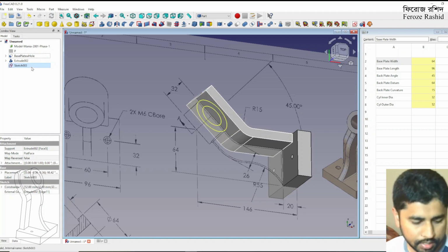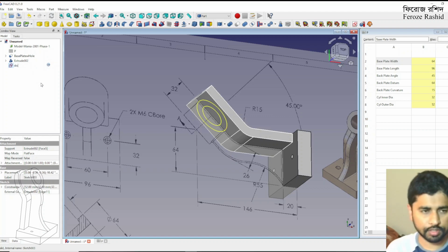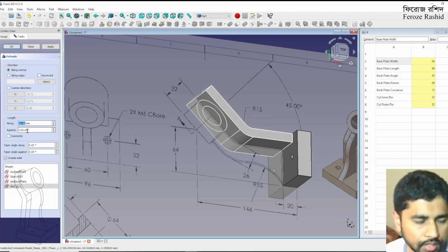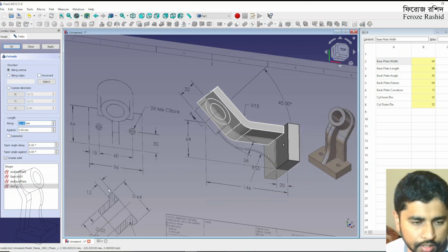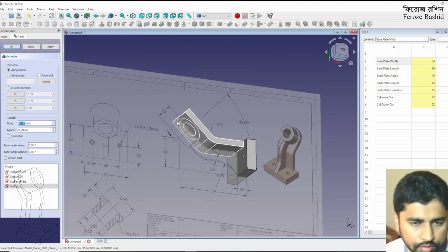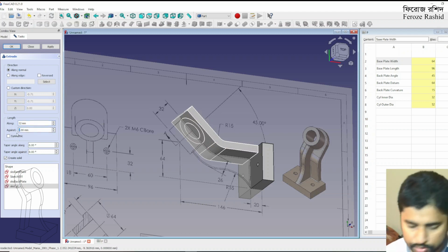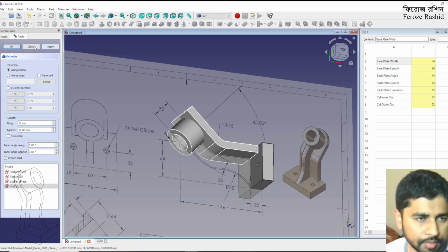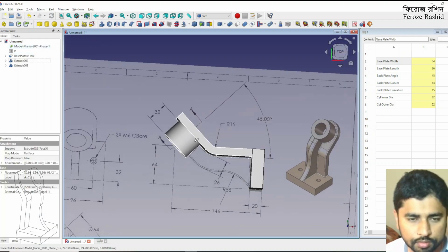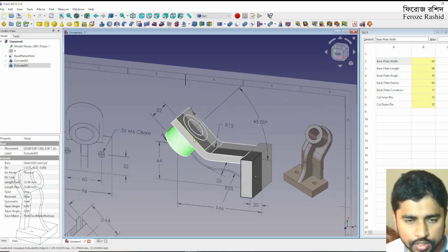With that, I want to rename that as sketch cylinder, and extrude that. So that would be how far? I guess 32. But then I want to extend it back by the thickness of that plate, which is 12. I will explain in a moment why I did that. So now this cylinder extends up to here.